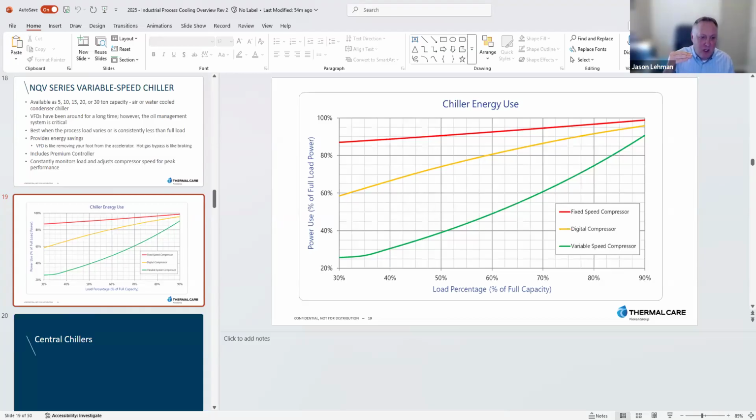If you cut the flow in half, that's basically cutting the heat load in half, and the compressors won't recognize that, so it'll overcool, your temperature will drop, and then the PID in the controller will react, and so you'll kind of whiplash a little bit. You generally want to keep a constant flow through the chiller, and that'll allow you to maintain a tighter temperature range, which is what most manufacturers are looking for. Fluctuations create variability, which creates bad products. Good to know.